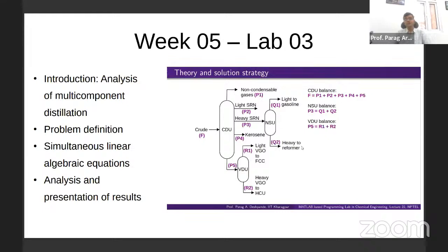And how do you actually go about solving this? It is, in a sense, a very simple material balance problem. Your analysis involves overall mass balance. These are the overall mass balance equations. All the flow rates were given as mass flow rates. We spent quite a good amount of time appreciating why it should be mass flow rate rather than volumetric flow rate.